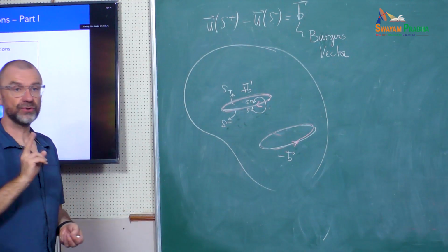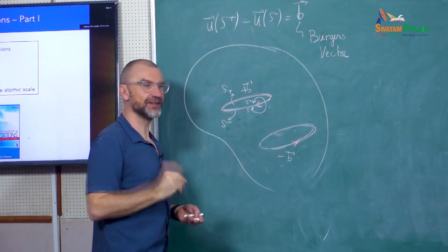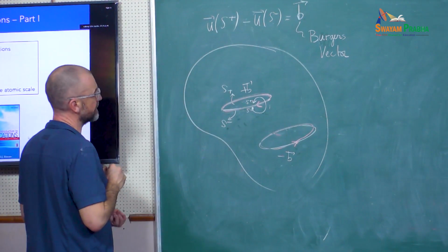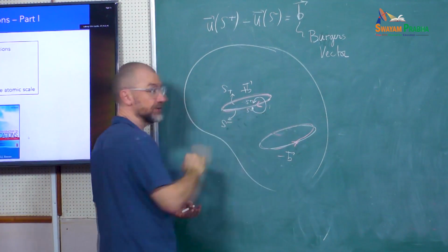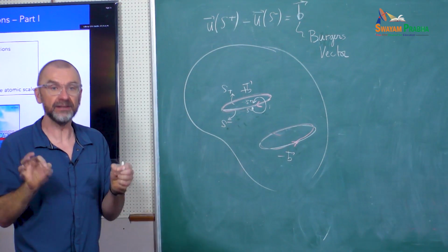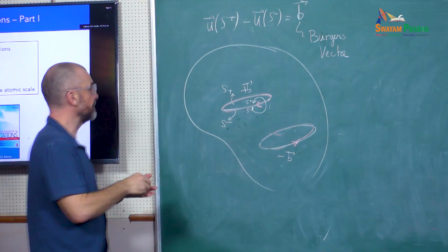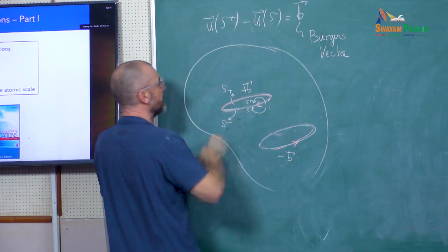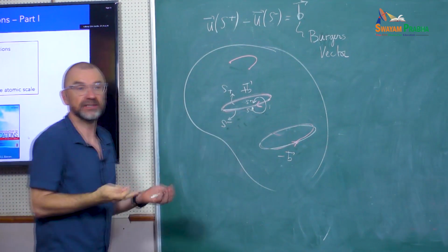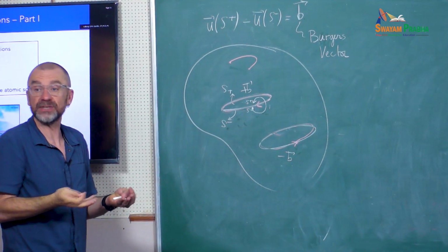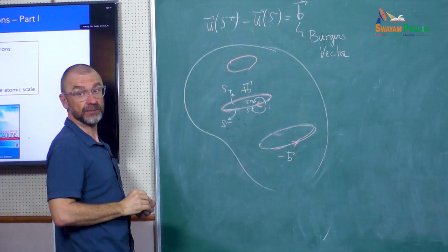Okay, there are two consequences from that. So the first one, although we discussed it a little bit with Anand yesterday: since the dislocation is the border of a cut surface, a dislocation cannot end in a material. Because you cannot cut a surface such that the border starts here and goes there, and then there's nothing behind. It's topologically impossible. So a dislocation cannot end inside a crystal.